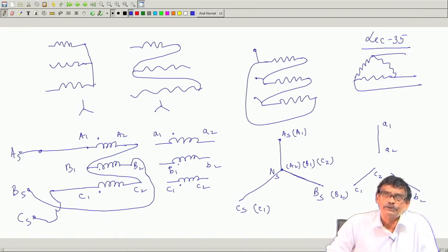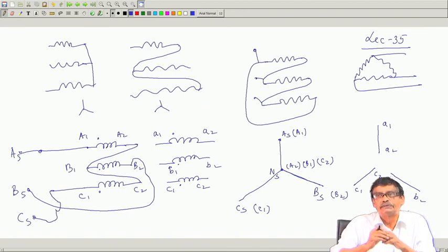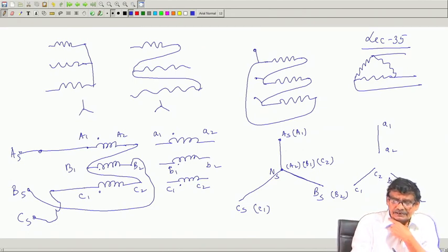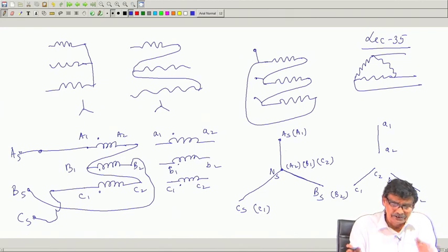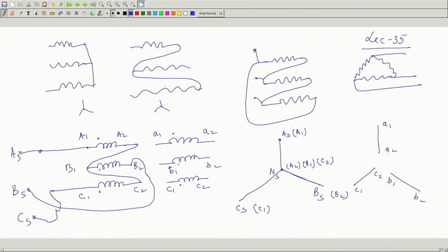Now, the point I want to make is, without doing polarity test, you should never try to connect the 3-phase transformer either in star or delta, and the difficulty that will come, that I am telling. Somebody connects like this, although the actual polarities are like this, but he does not care, star connection, okay, connect supply. Then look at the individual applied voltage across the primaries.